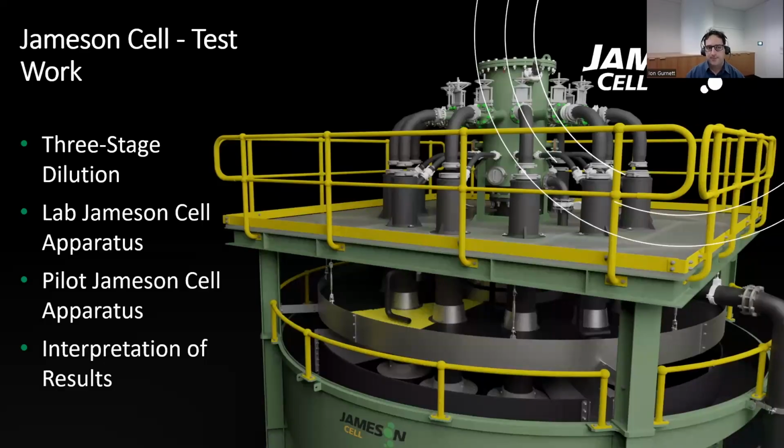Now, test work. I'd like to go over test work, and in this area, this is something that's really, really important to me. I'd like to really highlight the benefits of the three-stage dilution cleaning test, i.e. an entrainment test, go over some of the lab equipment that you have, piloting, and a very quick intro into how to actually interpret some of these flotation results.